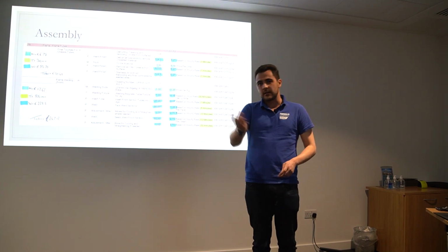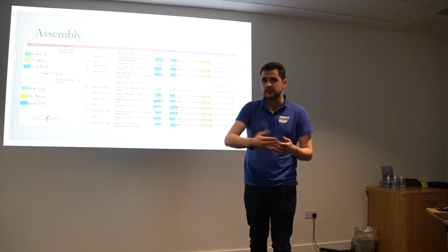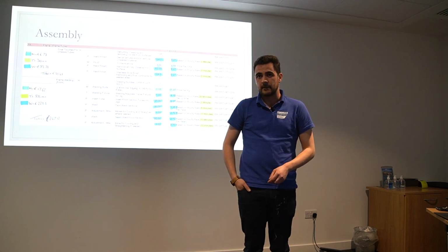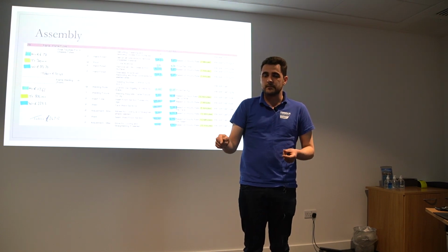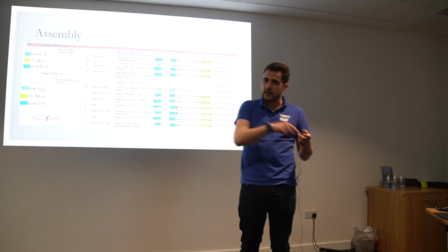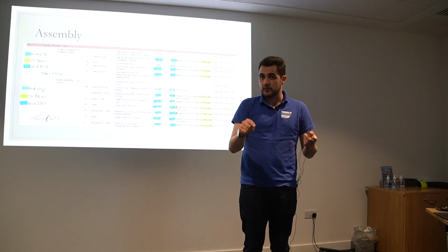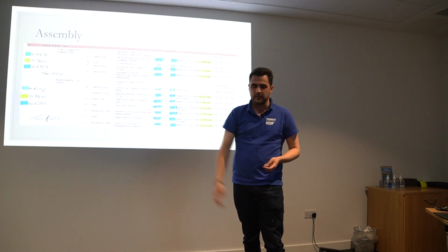So how would you then go about costing your plate? So we're going to say you've got a flat plate, we're not going to say you've got a full chassis, so let's go for that. So where would you start? Probably start with patterns and molds as a starting point. Yeah, so we're going to go pattern, mold, part, or pattern, part. So if we're going to go scalability, we'll go pattern, soft mold, hard mold. Yeah, okay. Soft mold, so up to short runs. We're not going to go further than that.